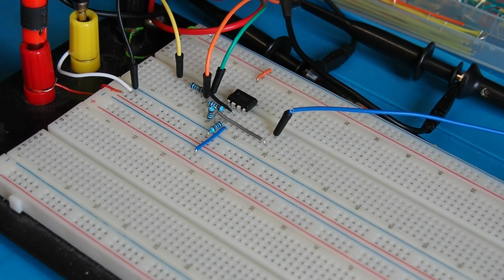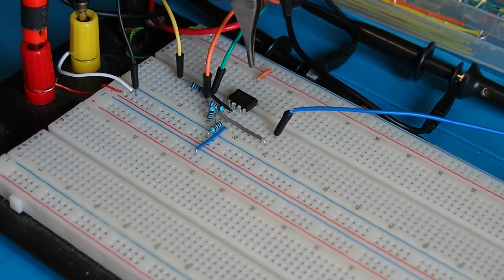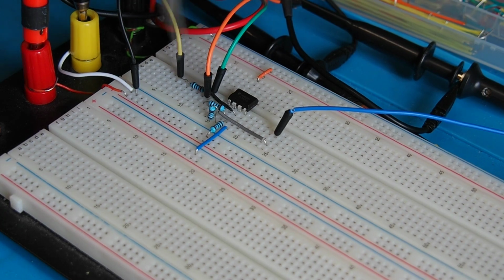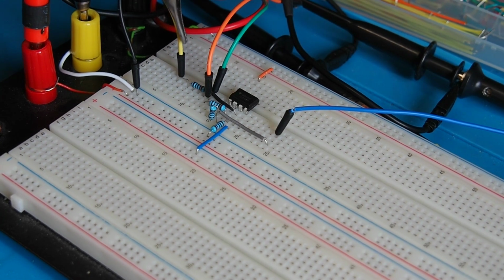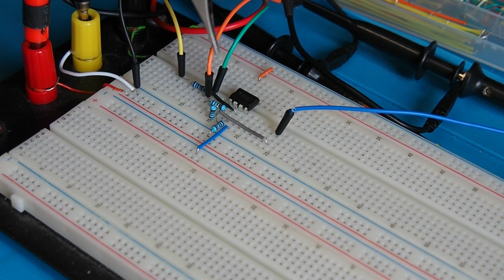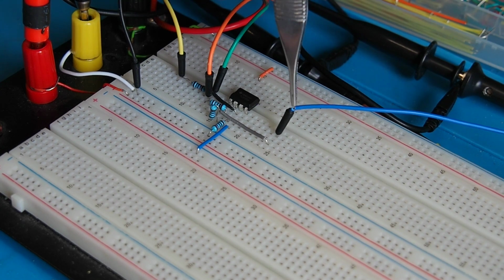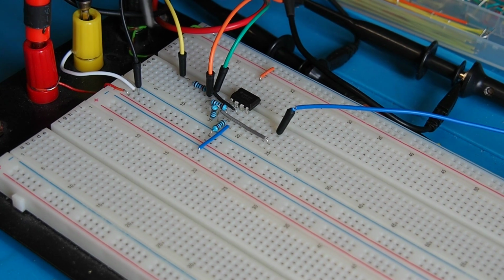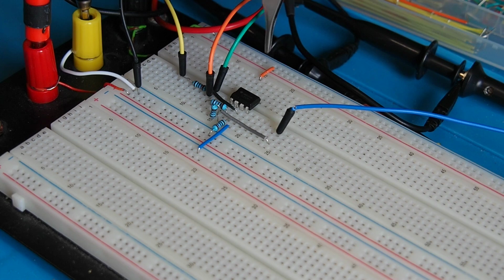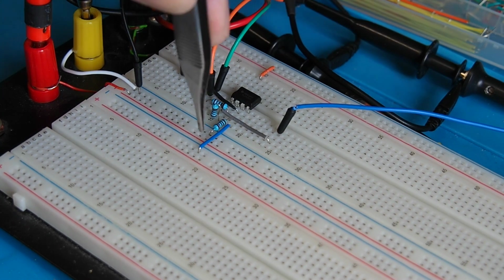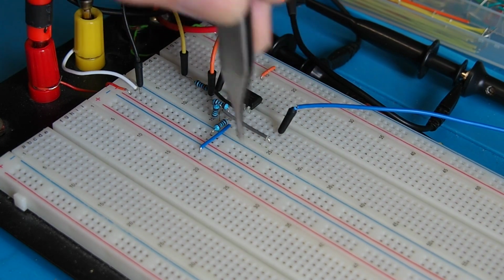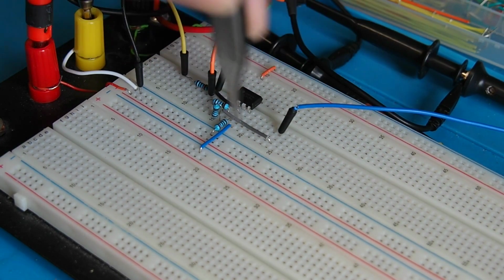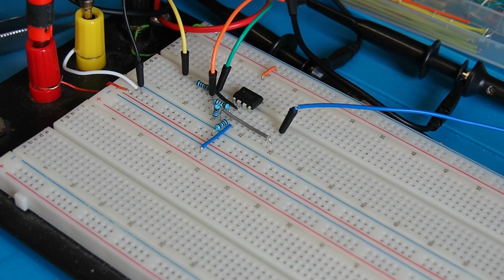Here's the difference amplifier set up on the breadboard then. So integrated circuit there, as you can see, resistor network as per the slides you've just been looking at. Input 1 is via that yellow lead there, input 2 via that orange lead there, and the output taken off the blue lead here. All those are connected to various scope channels, and just for completeness, you've got positive supply there, negative supply there, and the zero rail is actually this bus just running along there. Right, let's look at the scope view.